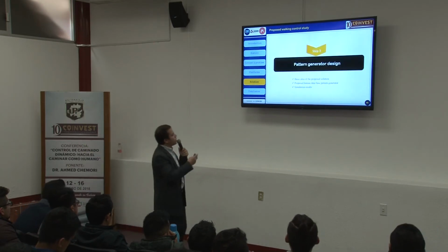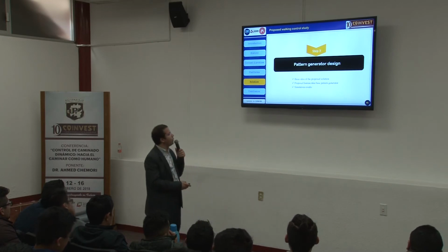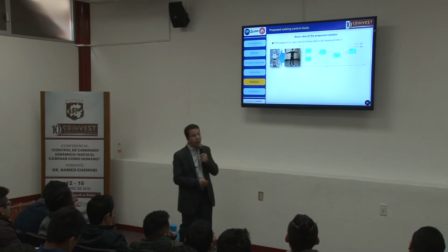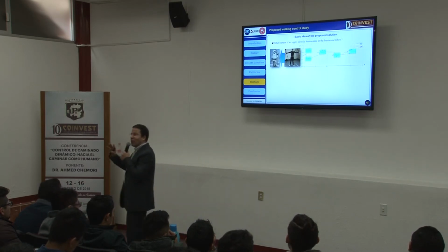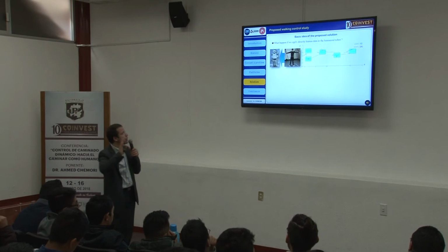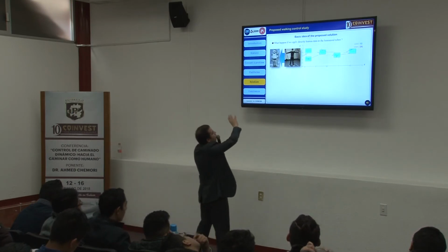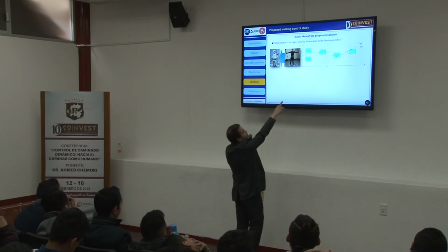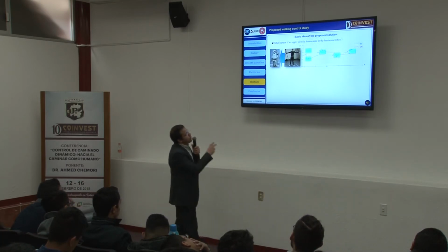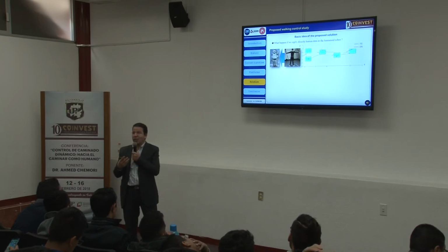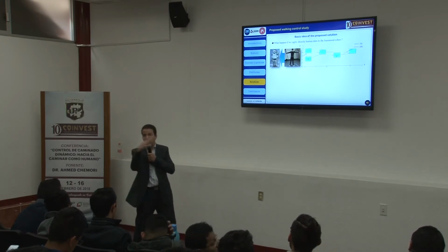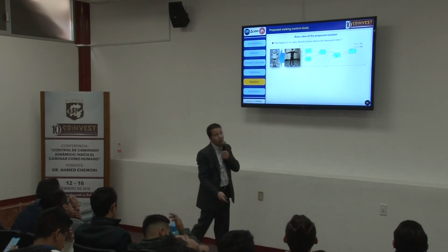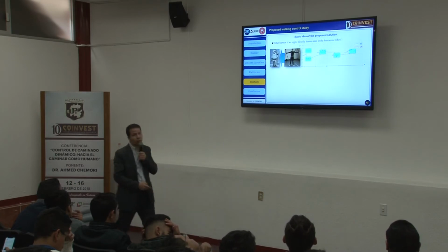The third step now is the pattern generator design. We proposed firstly a basic idea, then we tried to see the result. The result was not so good, and we tried to modify it to get a good result. Initially we tried to apply directly the data coming from the human on the robot. And here, as you can see, is the result. The walking motion is unstable. So the robot will fall down if we apply it on a real robot. Why? Because as you can see, the ZMP is sometimes outside of the polygon of support, so it was not so good.